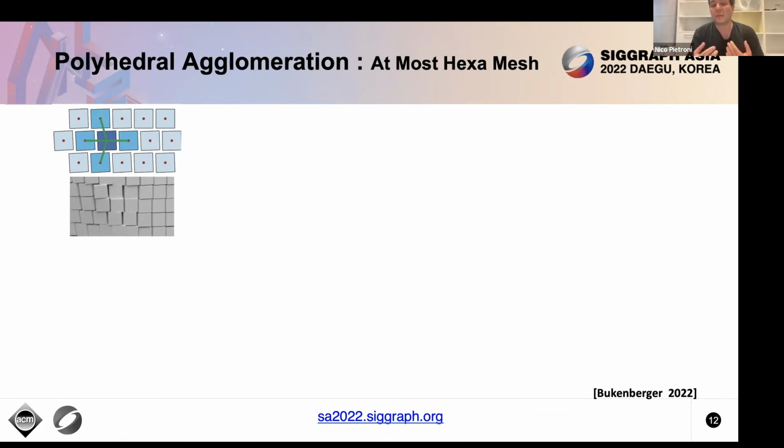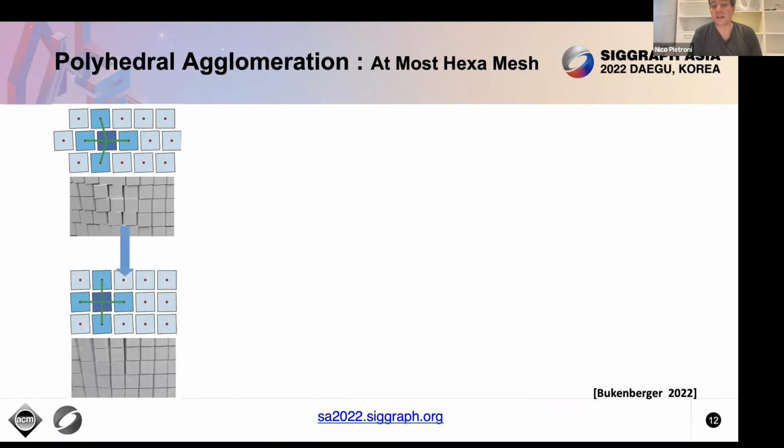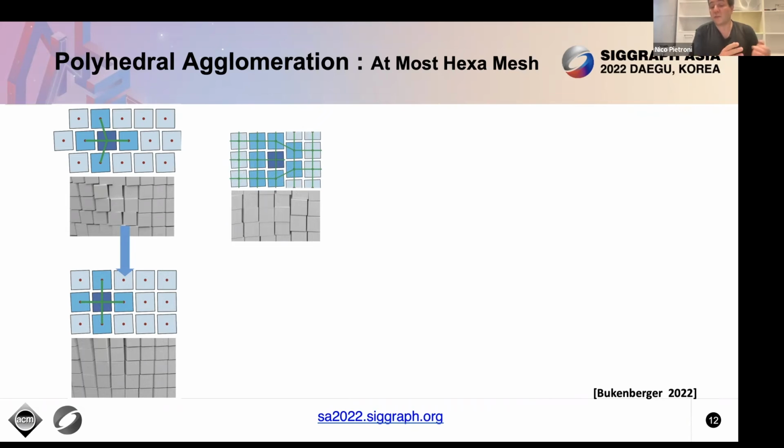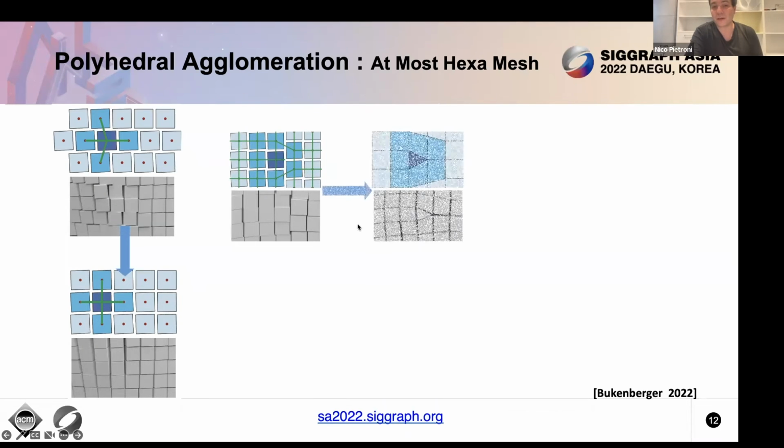When you have these local patterns where you can always find a set of neighbors for each cell, this immediately boils down to a nice regular hexahedral tessellation like this one. But when you have some strange situation where you have a reduction of the density from one side to the other, then, in order to have a conformal mesh, because the one you see here is not conformal, you necessarily have to add non-hexahedral elements and change the resolution from one to another.